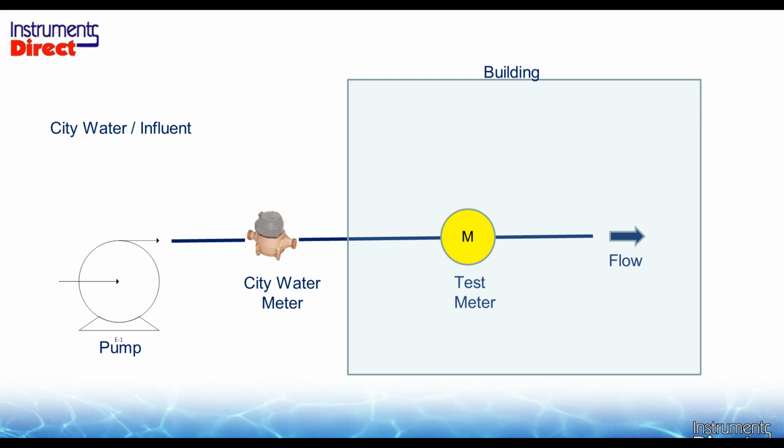Now, 1.5 gallons times 2 is 3 gallons in an 8-inch pipe. And in an 8-inch pipe, 3 gallons is not going to blip up on the radar. 3 gallons is like 0.01 feet per second as a reference. So most flow meters don't go that low. So you won't see a toilet flush, you won't see minimal use on a large city water meter application, and there's the difficulty in monitoring that application.